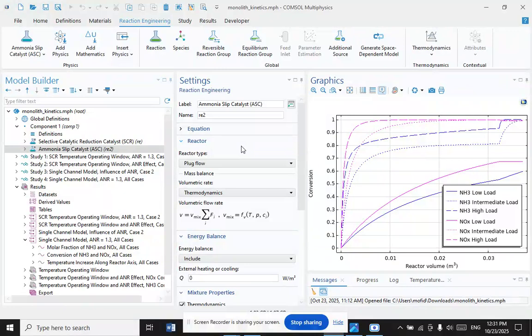Historically, medium and heavy-duty diesel engine emissions were not regulated until 1987, when the first California heavy truck rule was introduced, capping particulate emission at 0.6 g per bhp-hour. Since then, progressively tighter standards have been introduced for light and heavy-duty road-going diesel-powered vehicles and for off-road diesel engines. Similar regulations have also been adopted by the European Union and some individual European countries, most Asian countries, and the rest of North and South America.